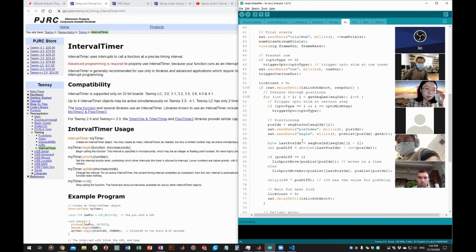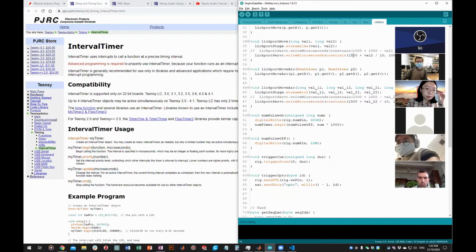Maybe the animal has started licking, and somewhere in the middle of the licking, time is up. Well, not the licking time is up, but the previously set timer limit is reached. And this function gets called just like an external interrupt by the licking. But here what we are doing is very simple: we just digital write to turn that pin to low.